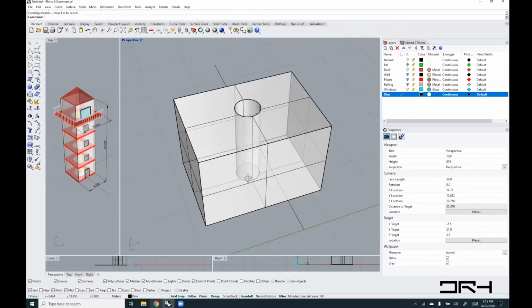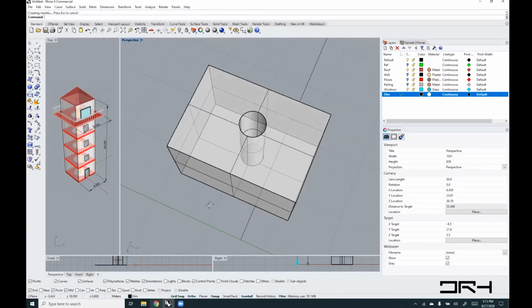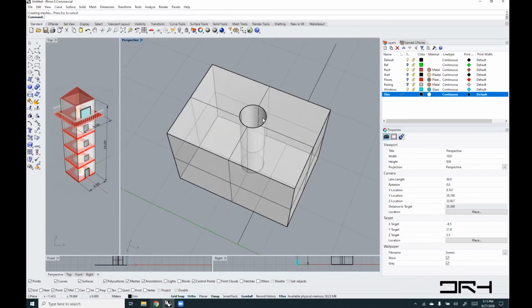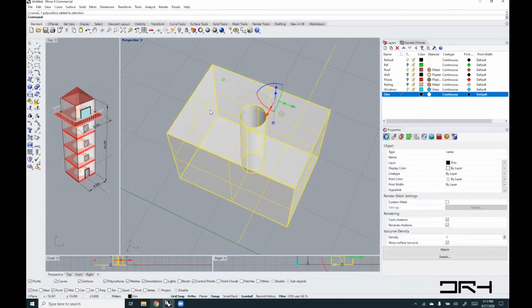But with this one you select only one curve, but multiple objects to cut through. While with make hole, you select multiple holes and one object to cut through, if that makes sense. No, that's cool. Also, is there a function to the ISO curves? Because from my past experience, they've been pretty useless.